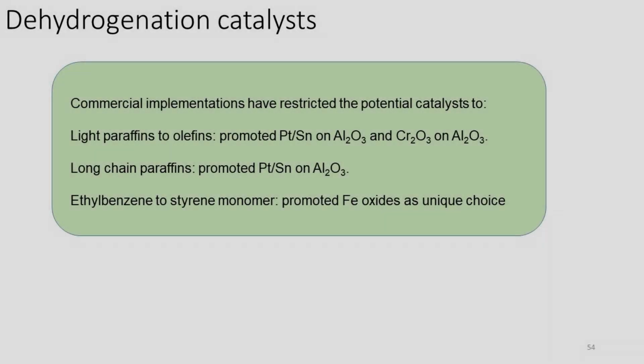Let's talk about dehydrogenation catalysts. Two main types of formulation are typically used for non-oxidative dehydrogenation of light paraffins: noble metal-based and metal oxide-based catalysts.